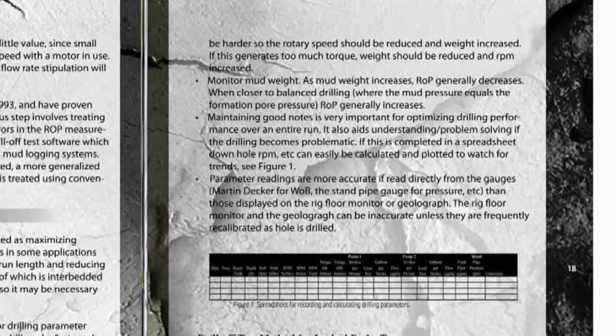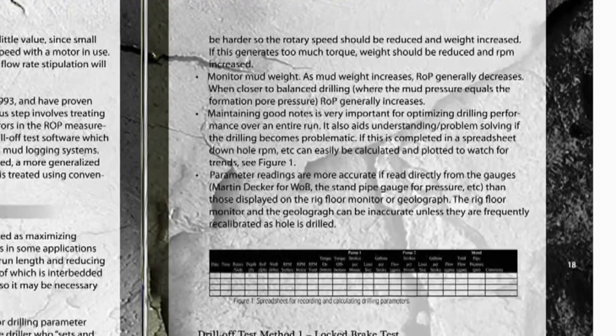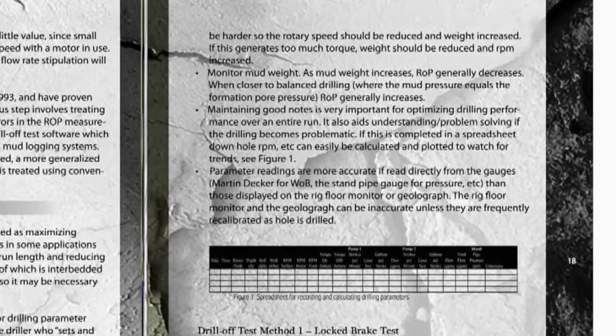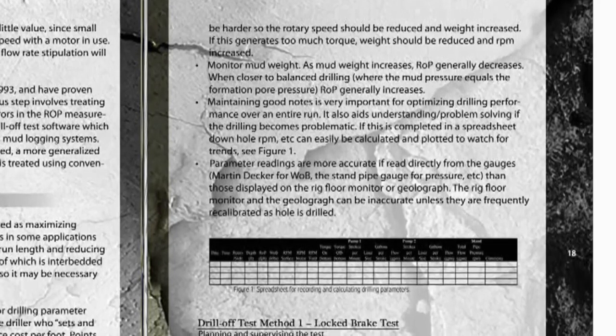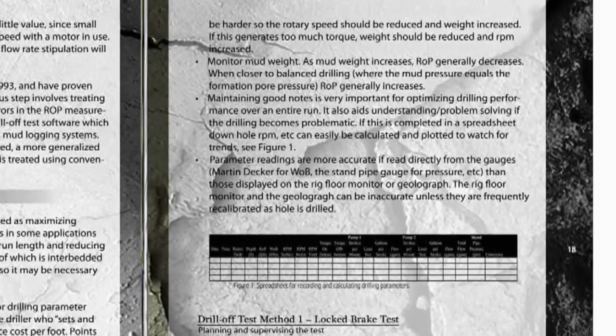Monitor mud weight. As mud weight increases, ROP generally decreases. When closer to balanced drilling, where the mud pressure equals the formation pore pressure, ROP generally increases.